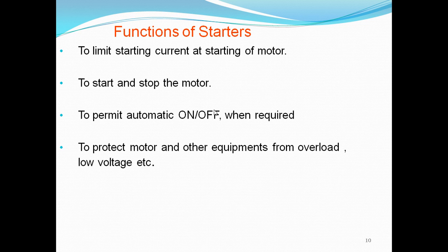Another function is to start and stop the motor. Next is to switch automatically off and on when required. Next is to protect the motor and other equipment from overload, because of this motor, other connected applications will be affected.